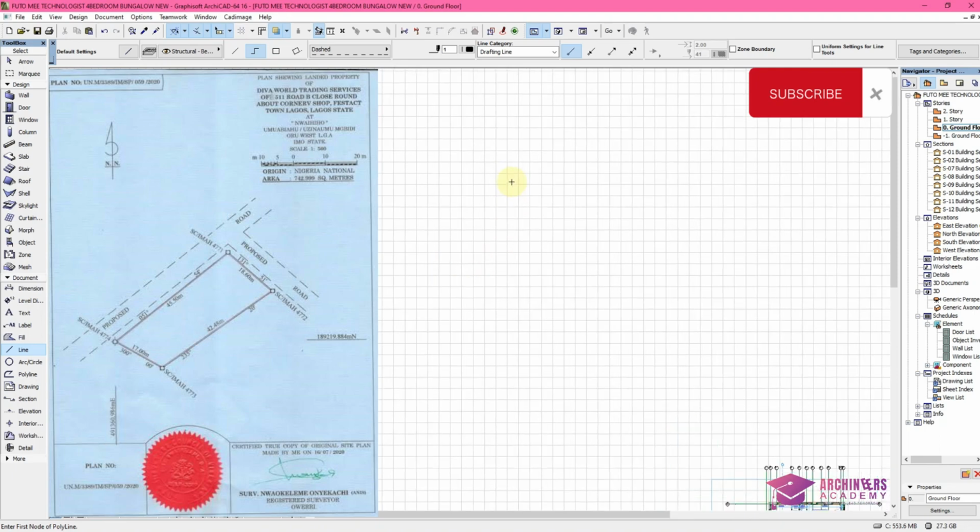Right now we'll be showing you how to draw a survey plan with your Archicad. After you design a building, or even before you design, you have to know the land measurement and place it correctly in the Archicad. And when it comes to an accurate land measurement, it has bearing and distances, not just only distance. So the lines are not always at 90 degrees, so therefore you have to draw it accurately. So to draw it accurately, you have to actually use angles and bearings.